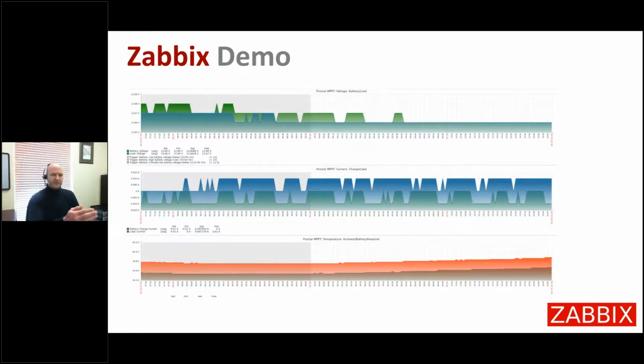If you start seeing events or thresholds being crossed, such as low battery alarms or load disconnects, which means your site is having trouble staying operational, you can start to anticipate a battery replacement. If you can see temperatures during a certain period in a certain region rise above 50 C within the cabinet, you're going to know that you've got some high temperature issues that may affect the operation of the equipment.